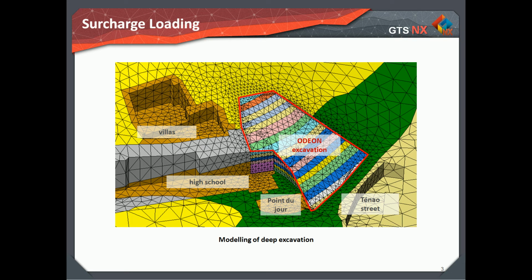The surcharge loading to be used should be compatible with the particular situation being modeled. However, in most cases, a surcharge loading to model construction traffic, storage of material adjacent to a retaining wall, and so on, should be included. The British Standards Institution, for example, recommends that a surcharge of 10 kilonewtons per square meter should be included to model such effects. The pressure of compacted fill on retaining walls may be a significant factor in the imposed loading. Clayton and Simons outlined an approach for calculating these pressures.